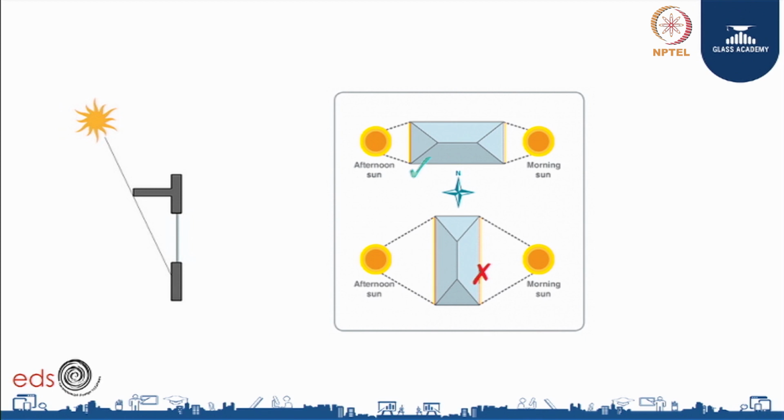If you do an orientation where the larger parts of the building, as you can see here, face east or west, then the rising sun or the setting sun are very low in their altitude, and you will get streaming sun into the building, and that's a very problematic situation, because to control the sun coming at that low angle, you will almost need to block it completely. You will need a screen, or you need blinds, and that will create problems with daylighting.